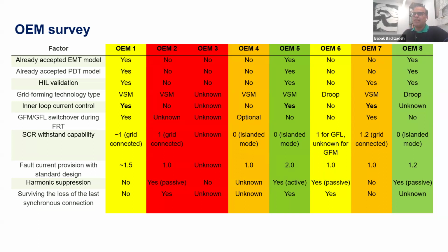But I think what we need to be conscious of is that SCR with a stand of 0 does not happen during interconnected system conditions. Not only because there is an interconnected system, so SCR cannot be 0 anyway, but here there is a significant difference. In islanded conditions, the requirements for different aspects, whether fault ride-through or active reactive current injection, are very different. When you're coming to grid connected mode, those requirements are tighter.